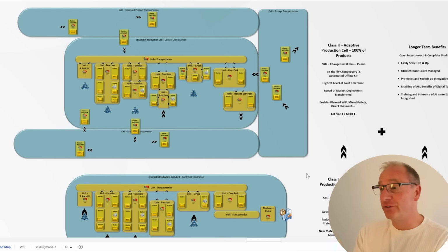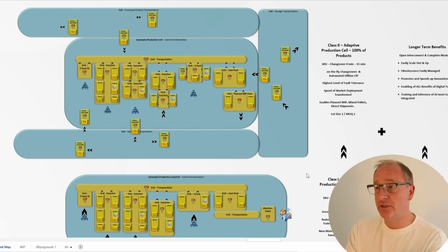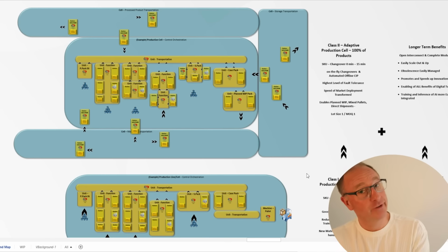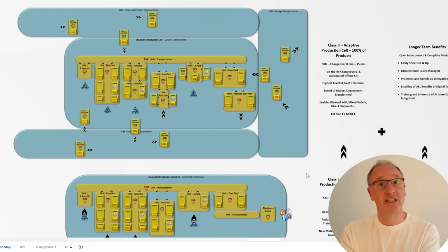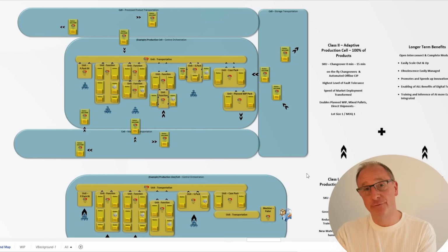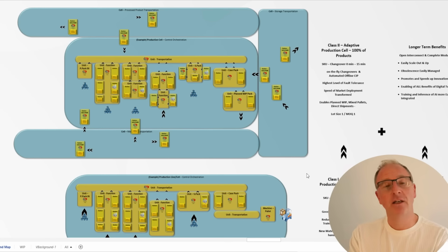So back to where I was. Changeover time can be minimal, right? That's not an issue. When we split the functions, we can handle safety a bit easier, actually. Fault tolerance is as good as it gets. Because in actual fact, if you have a serious fault with one of the units, you can just swap it out with another one. It'll inherit all the appropriate parameters when you plug it in, and you can be up and running pretty quickly.